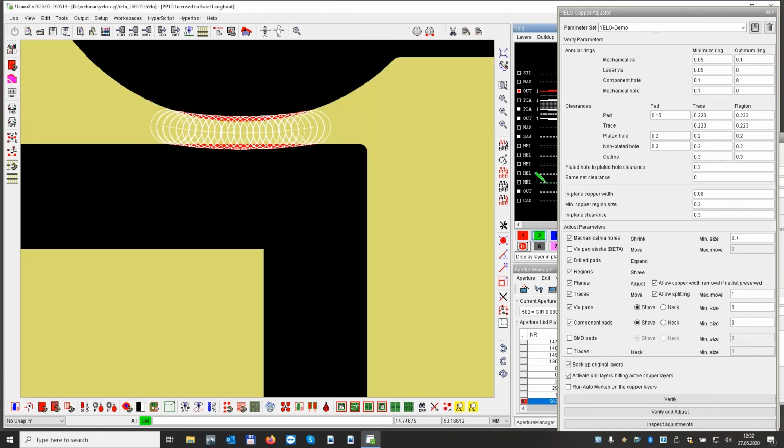The original layer looked like this, where we have less than 80 microns, because what we used for the drawing is 80 microns, so this would have been 50 microns or something like this. This is again the least invasive method. Otherwise I could also say I take this bridge completely away, but it would be more invasive, so we choose to use this repair method.